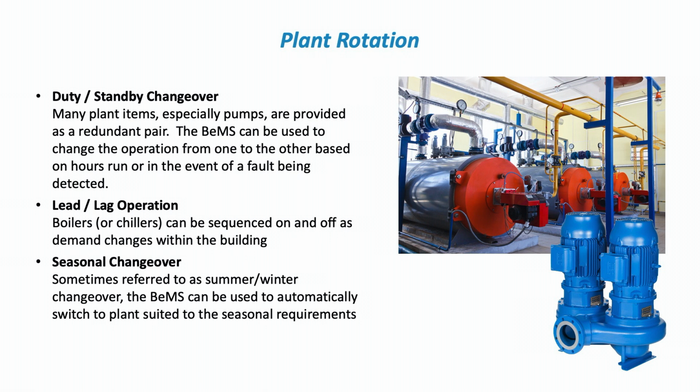We can also have lead lag operation. Lead lag is slightly different from duty standby. Boilers and chillers need to be sequenced. If you've got, as is shown in the drawing here, 3 boilers, you would want to sequence them on based on the demand in your building. You don't want to just bring them all on. So we can use our BeMS to sequence those on.